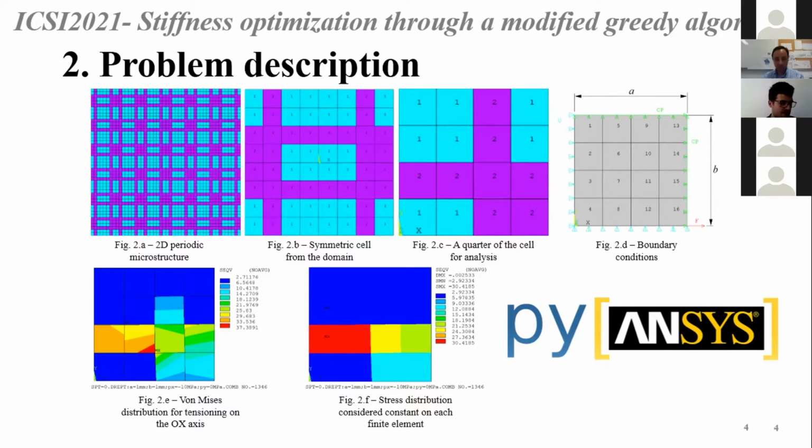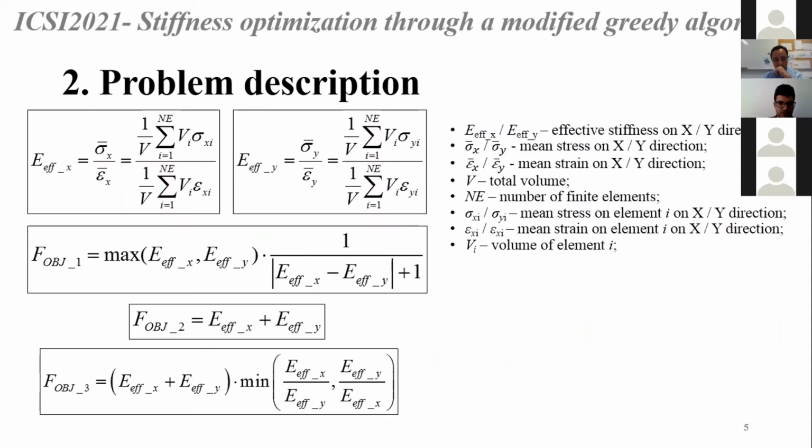For a linear elastic analysis, the stress distribution for each finite element cell is variable if we do not consider a reduced integration element or stress mediation of a whole element. But to further simplify the results, we consider that the stress is constant on each element.